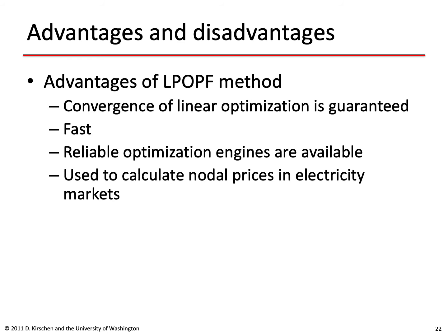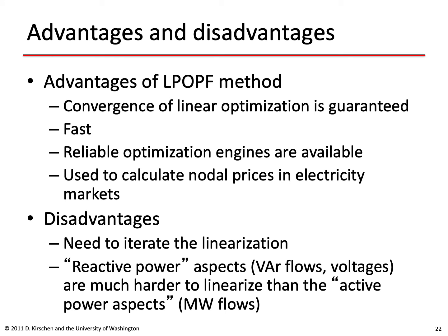The disadvantage is that if you want a really accurate solution, you may have to iterate the linearization, and that the reactive power aspects, for example, the VAR flows and the voltages, are much harder to linearize than the active power aspects, such as the megawatt flows.